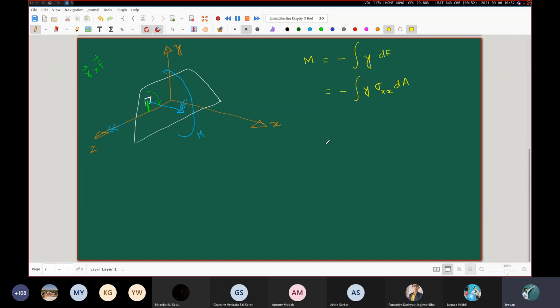You see, earlier I had mentioned that we are talking about pure bending, meaning that in terms of the external loading that is exerted on this body, we have this kind of a M. But we do not have any axial force, we do not have any torsion. So let's consider the axial force. Axial force is 0. This is what we are saying. Now let me write like this, and let me not write F because I've already written F here. Let me call that P. So P is the axial force.